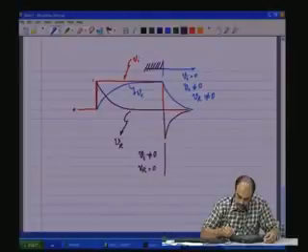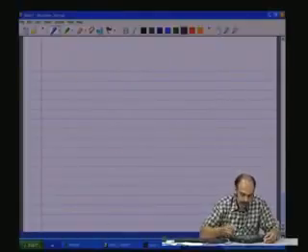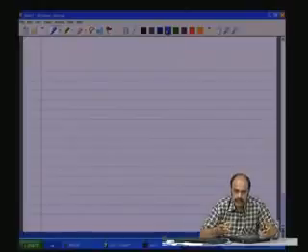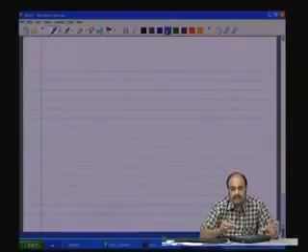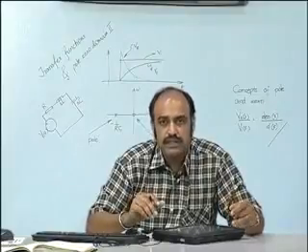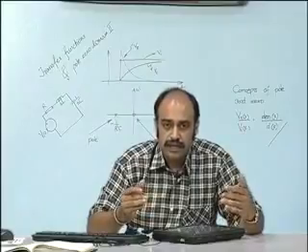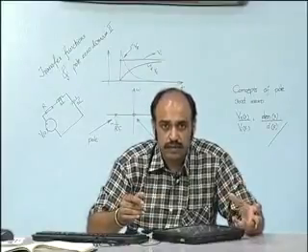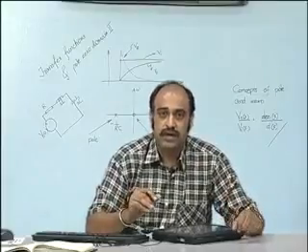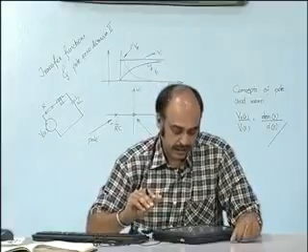Now, this procedure of analysis we shall use: obtaining the state equation, and then from there the sinusoidal steady state equation, and then from the state equation again the transfer function, and then taking it to MATLAB, appropriately converting the state equation to the transfer function, and then doing the analysis in the three major domains, which are the time domain, the frequency domain, and the pole 0 domain. This would be the standard process to follow for analysis.